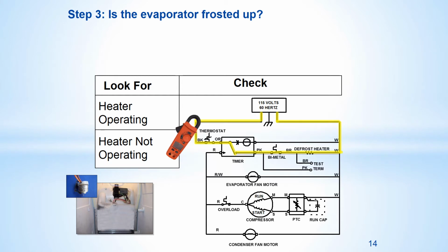Please note that if you do see a bimetal in this condition, remove the power before touching it, as water may have already entered it and it is a shock hazard. Be aware that the refrigerator will normally remain in the defrost mode for a few minutes after the heater has turned off or cycled off to allow for defrost water to drip off the evaporator and into the drain pan before starting the compressor.